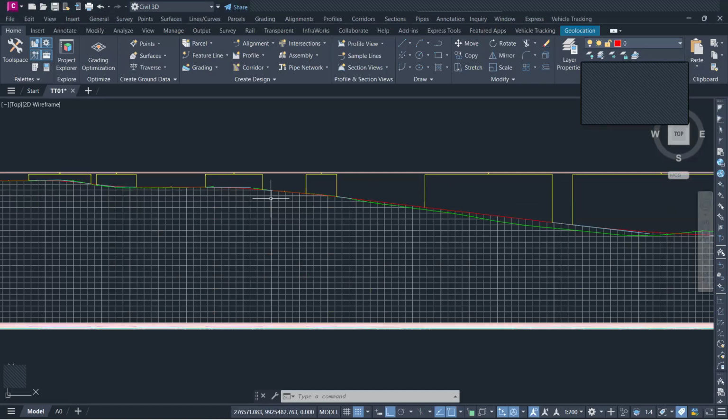This is again why we provide markup in cost estimation, especially when you are preparing the engineer's estimate, when you are bidding, and even when you are budgeting. If you're working from the government side, you need to provide markups sometimes of up to even 20%. The rule of thumb in the industry is around 15%, 10%.